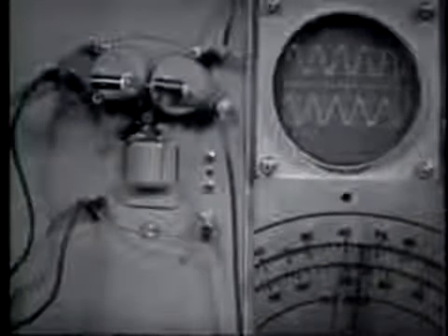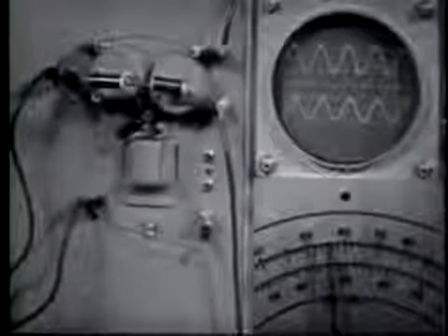Now let's check the frequency response of this circuit and see if we have indeed improved it. All right. Notice now that I only have to go down to about 550 hertz and I have maximum output from the filter. The same is true on the other side of the frequency we wish to reject. At about 650 hertz, I now have maximum output from the filter. So I'm now rejecting a band of frequencies much closer to 600 hertz. I have indeed improved the frequency response of the filter.